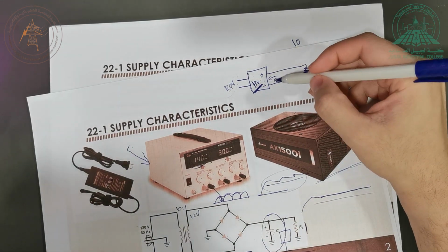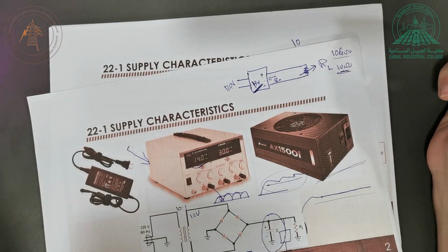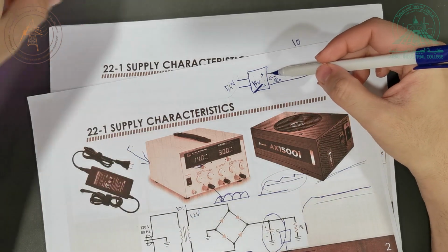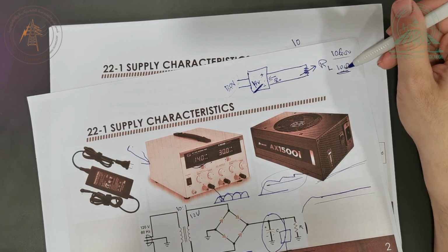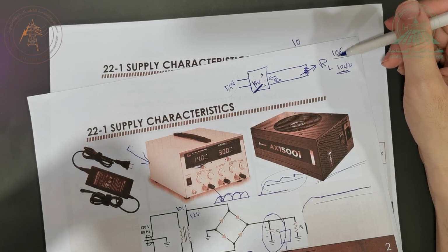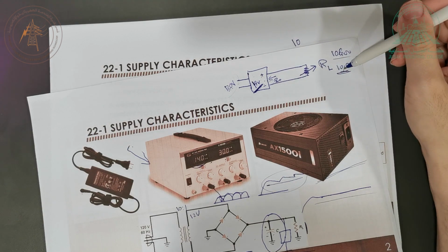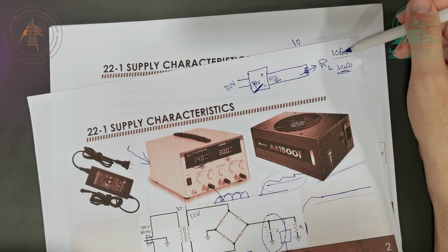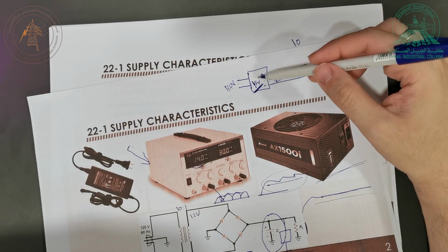So you are going to reach a point, even if you can make it as small as possible, because this resistance is actually very small itself, that's why you are going to get these fluctuations. That's why this internal resistance now is going to absorb some voltage. So here in this case, this output resistance is going to absorb some voltage, and when you put 10 gigaohm, it's also going to absorb a voltage, but it's going to be much less than the first case, because in that case, the output resistance is much less than your load resistance. That's why in this case, all the output voltage will go here.